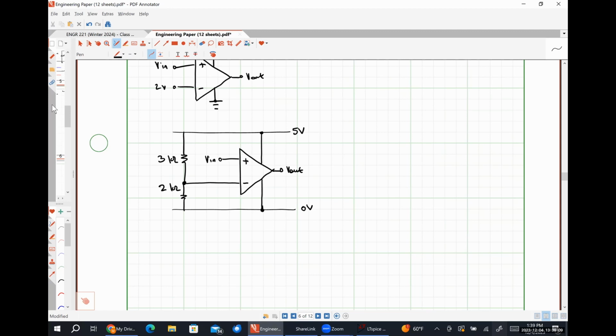Have you started on problem 2 yet? Yeah, I think I did. I just want to be clear here, you actually have an output resistance. The best way to take that into account is to treat your output stage as a voltage divider.